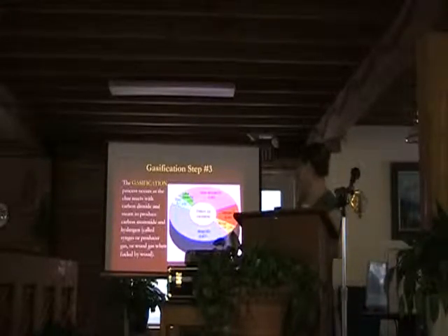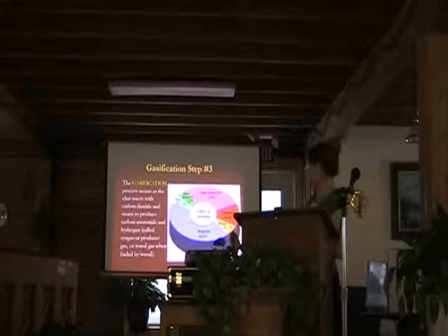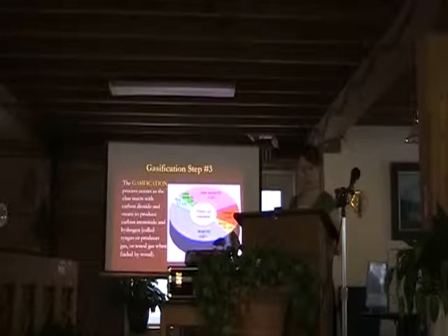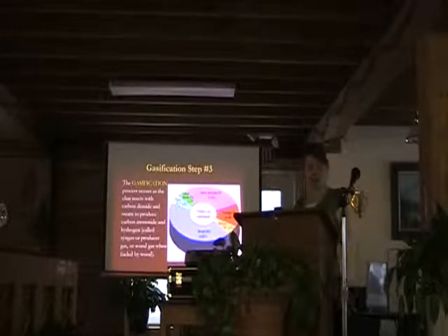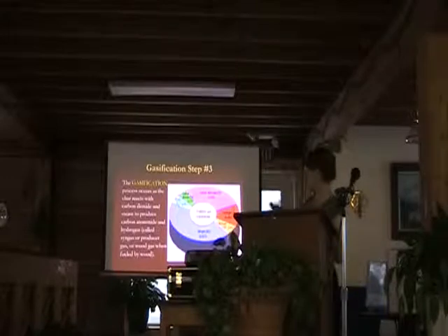Nitrogen is 45 to 60%. Water, which is really steam, is 6 to 8%. Carbon dioxide is 5 to 15%. And these are the producer gas constituents. In addition, the reversible gas phase water gas shift reaction reaches equilibrium very fast, balancing the concentrations of all of these elements.